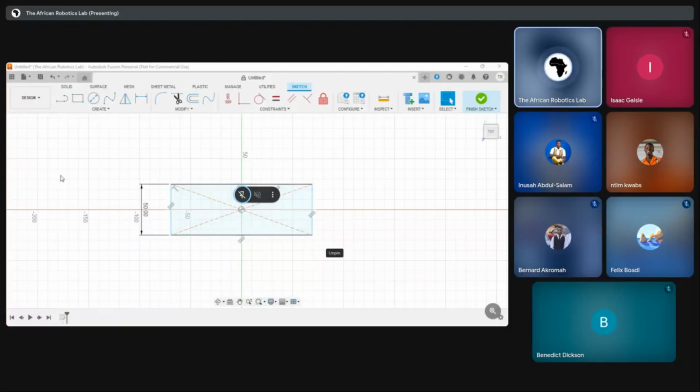So we have the sketch here, this particular sketch that we are working on. Whenever we have a pencil displayed on the sketch, it means there's something wrong with the sketch. It means everything in the sketch isn't working properly. It may be that there's a dimensioning that we didn't do, and that is exactly the problem. So let's correct that issue.